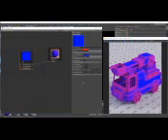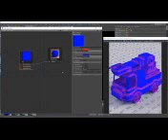The inside option is like enabling the invert normal option in ambient occlusion map from V-Ray or Arnold. Now let's change the calculate from to outside for now. Also, let's set the color spread to 100, occluded color back to black, and unoccluded color to white.